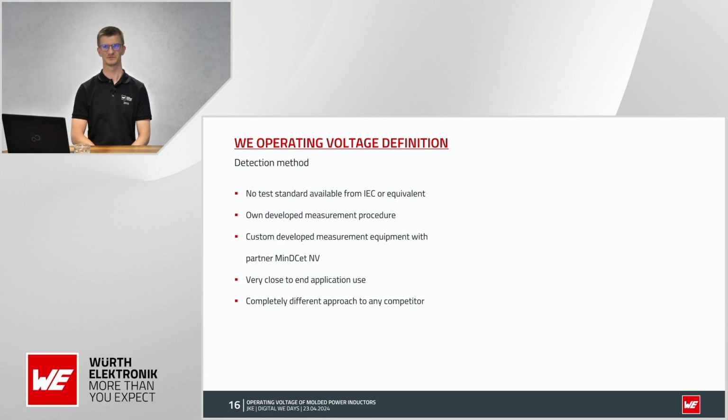Actually, there are some test procedures and detection methods available, also used by our competitors. We have also tested this, because mostly this is done with just some short voltage pulses that then detect the response from the device under test. But for the molded inductors, we have found that this is not really useful, especially for low inductance values.